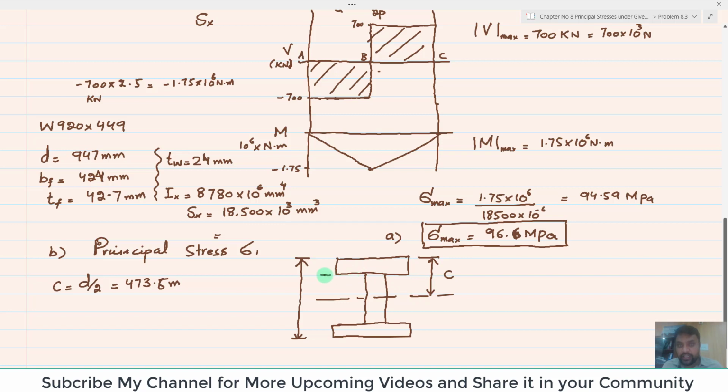Now we will find this value, and this value is YB. Clear? Because this is the junction between flange and web, this YB will be equal to C minus TF. This distance is TF, and TF is also given as 42.7. So 473.5 minus 42.7 will yield you YB, and this YB is equal to 430.8 millimeter.